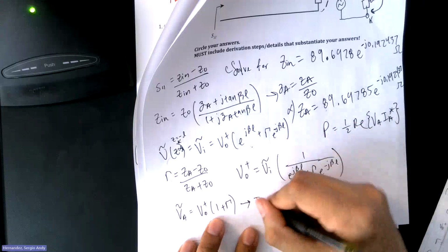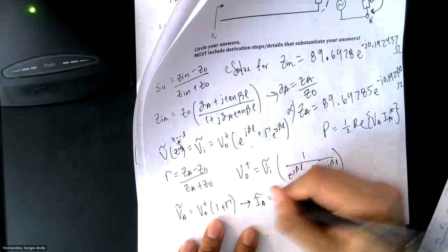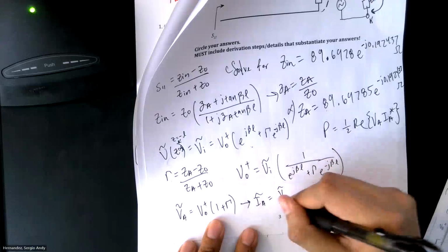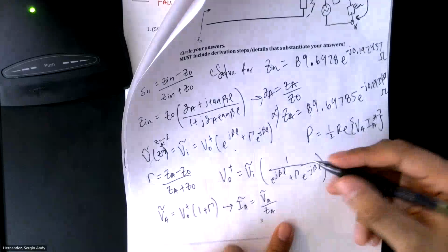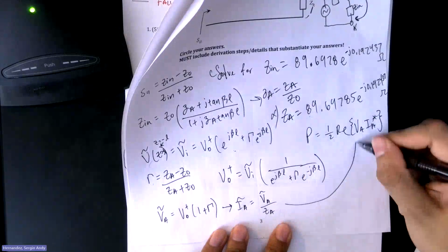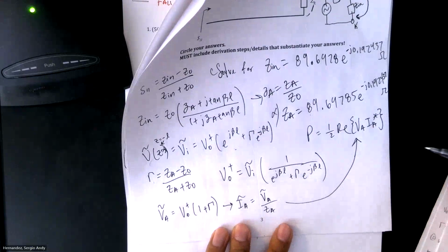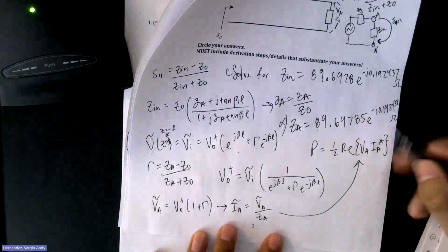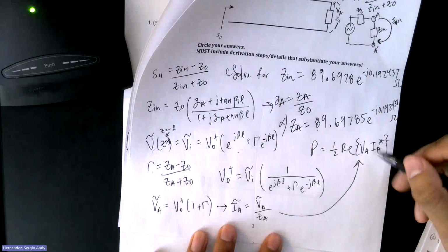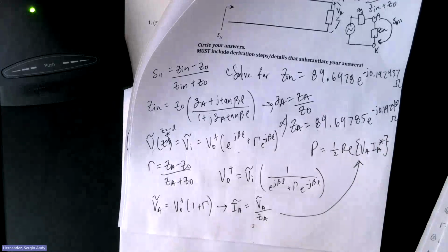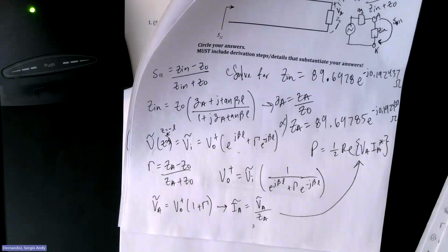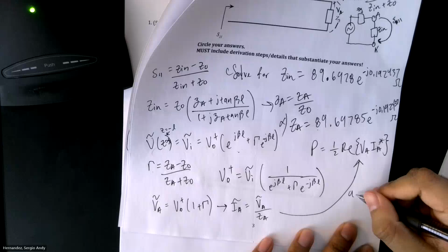And then you're able to get your current with this, which is your voltage over the impedance, right? Ohm's law. And then you want to plug it into this equation to get your power. Remember to take the conjugate of only the current for this formula. For example, we have A plus Bj, conjugate is A minus Bj. I'll write that down. That gamma.